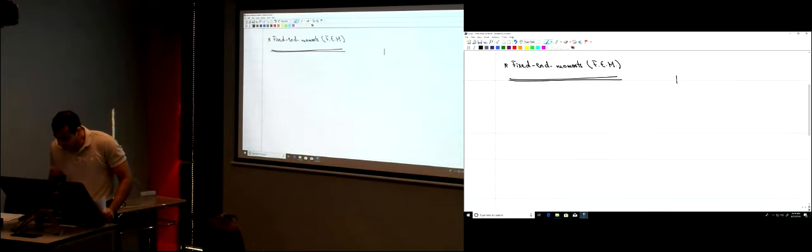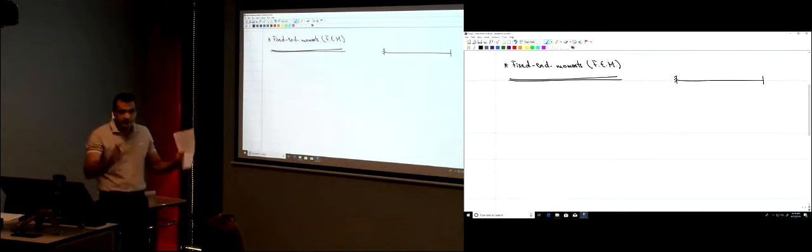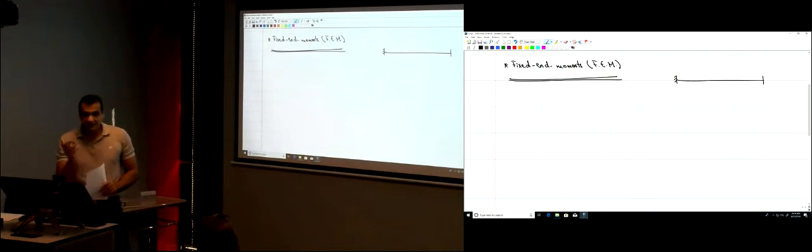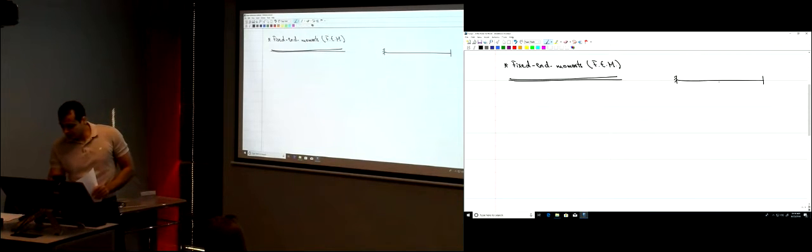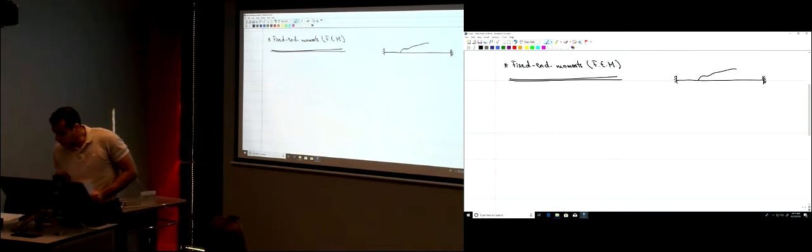If you have a beam element, there should be no supports there other than the end supports, to say that this is an element. If there is some support here, then this is an element, and here, this is another element, so two elements. So we have an element here, and there are some loads applied in this element.